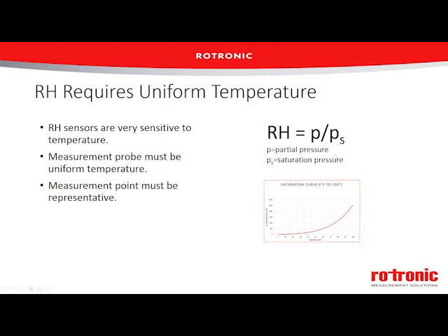So we have to understand that our relative humidity is dependent on the temperature in our space. So our relative humidity sensors that are actually measuring relative humidity, they are sensitive to this temperature, and they actually have a second order effect in that they have a temperature sensitivity beyond just the relative humidity and the saturation vapor pressure effects. Most often though, that part is taken up in the electronics of the sensing system itself.